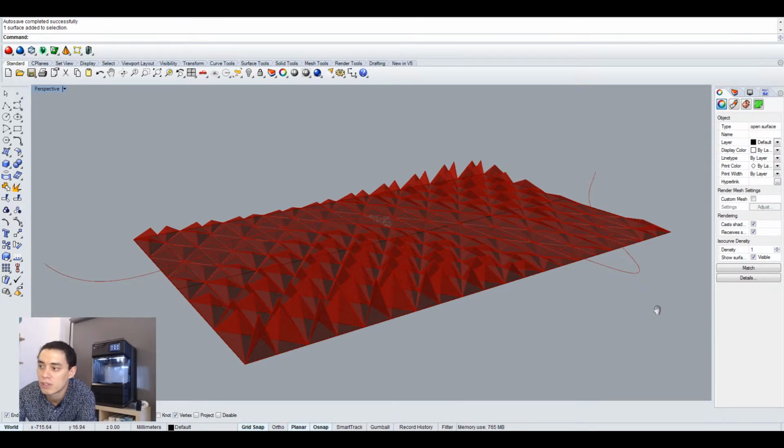Then from that surface, I'm taking some of the center points. For example, I'm finding the edges of those little triangles. Let me hide these for a second, so you can see how when I select something in Grasshopper, it becomes green in the Rhino window. So you see there are the green triangles, then they are red when they are not selected. The red overlay is just something that Grasshopper throws on top of my Rhino interface.